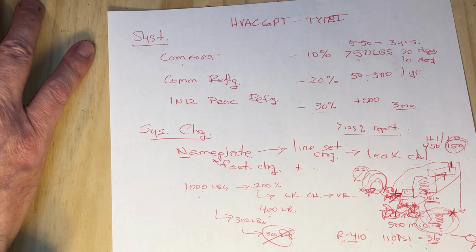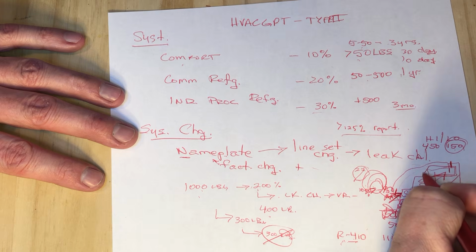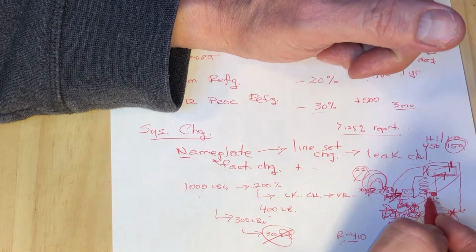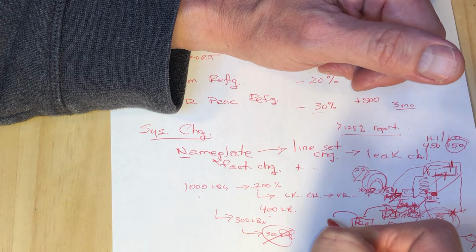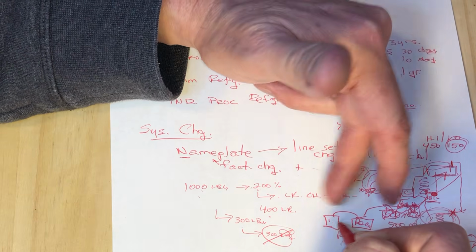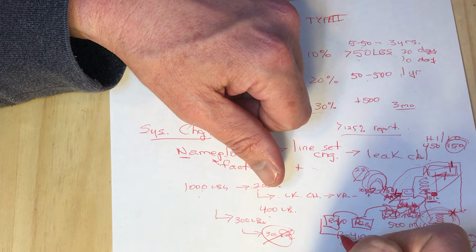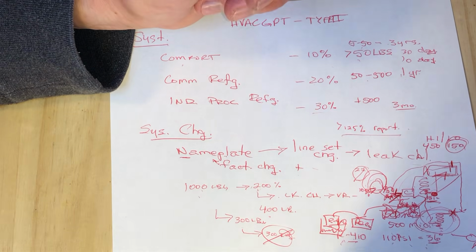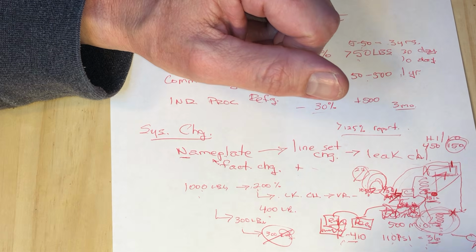So a couple other techniques. If you have recovery happening and you need a receiver, let's say you're doing the leak repair, it's above the condenser, you're going to want to get any refrigerant from the condenser outlet, if all this is on the same level with that recovery machine. So you're going to hook a recovery machine up now. This is our recovery machine, and that's going to go to a tank that's not mixed. Whatever the refrigerant is on the nameplate, that's the tank you should get. And that tank could be placed in a bucket of ice, and the ice will lower the temperature and the pressure, and make it easier for the recovery machine to pump the refrigerant in there. It'll speed the recovery process, just a little recovery technique.